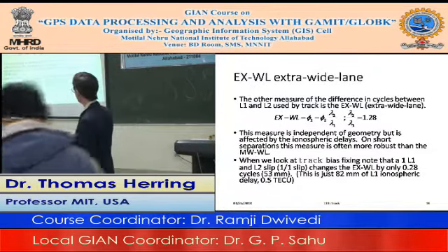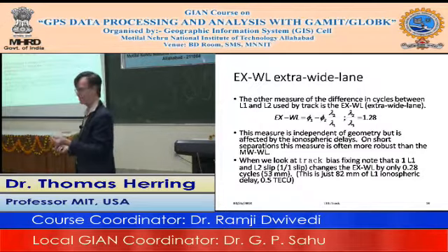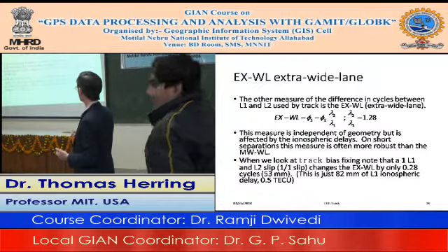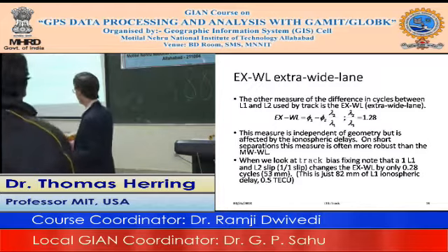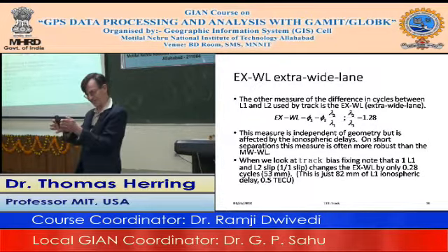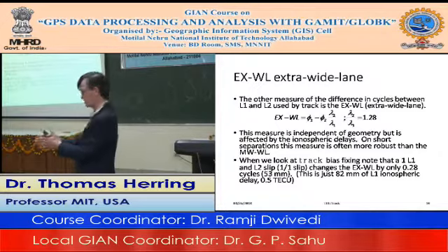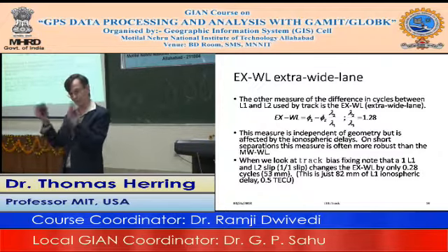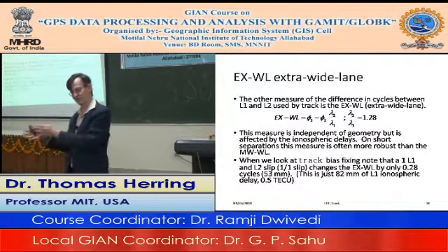And again, if the ionospheric delay is very, very tiny, this should be very close to 0. There is a subtlety, and again, when you start looking at track, you will worry about it considerably: the Melbourne-Wübbena wide lane, which we believe we can resolve usually quite well if the instrumentation's good, tells you the difference between the L1 and the L2 cycles.